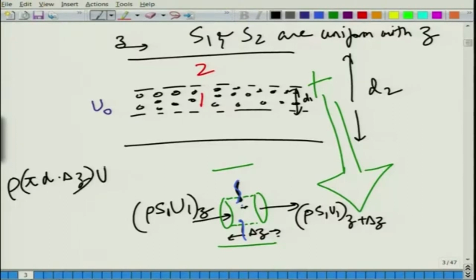We need to use a different variable, so let us call this u star. Another thing I want to mention is that we will eventually linearize this equation, we have not done that so far. So u star will not have a mean flow component, it is just a perturbation velocity, like the acoustic mass going out or coming in of this volume. u star is orders of magnitude smaller than the mean flow velocity. In a way u star is your acoustic particle velocity, but in the radial direction.